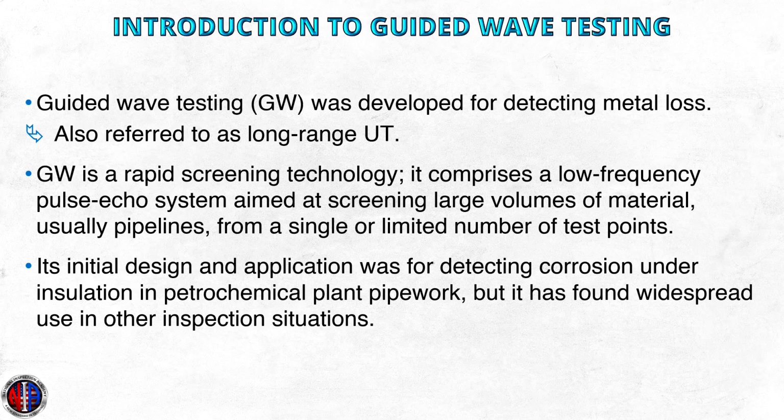The guided wave method does not provide a direct measurement of wall thickness or the exact dimensions of discontinuities. Quantitative volumetric inspections such as conventional UT or RT are recommended after initial detection of discontinuities, particularly for engineering assessments.